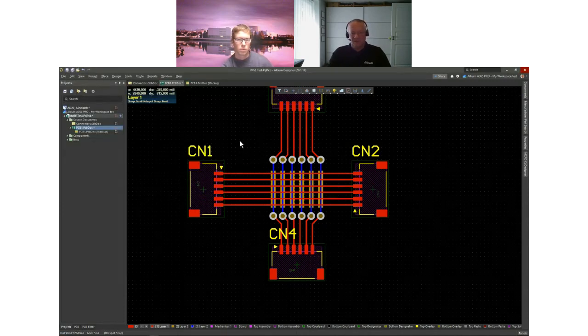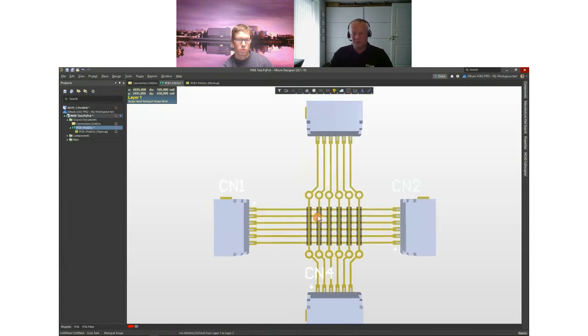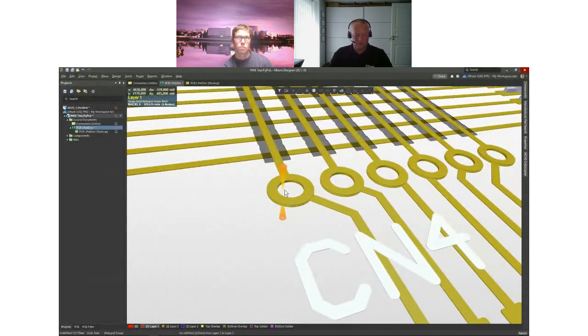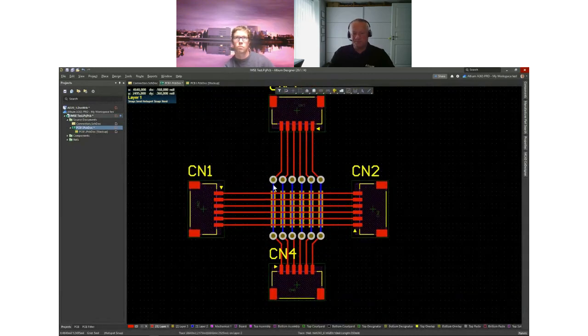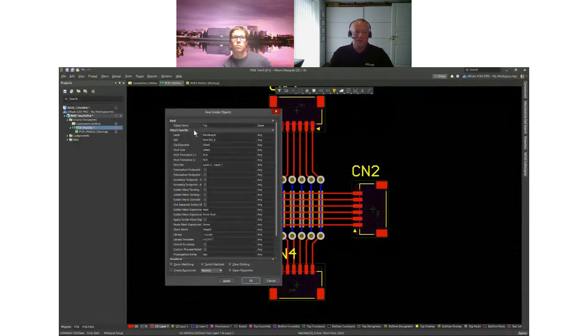And for the final thing I need to do with the design is actually changing the via slightly, because if you look at 3D presentation of it here, I don't actually want the hole in there. There's no need for it actually. So let's go back and change this one. If I select this one, I can ask the tool to select any similar object by right-clicking, say find similar object. The object kind should be a via. If this is the same, it will get selected and I will clear any of my other selections of it. So let's go for that.